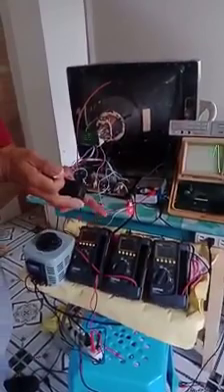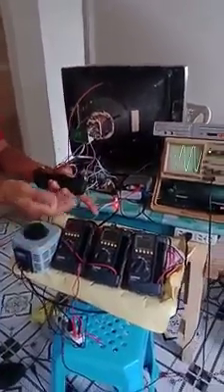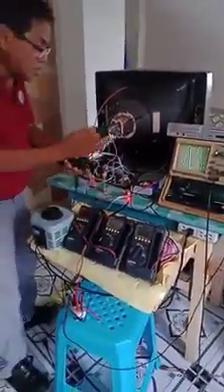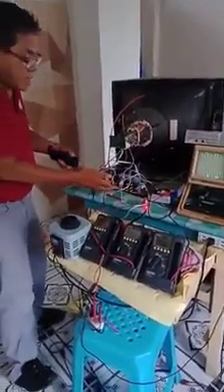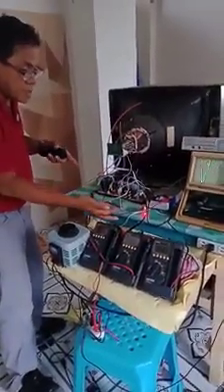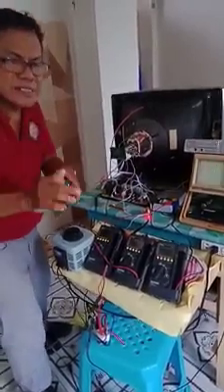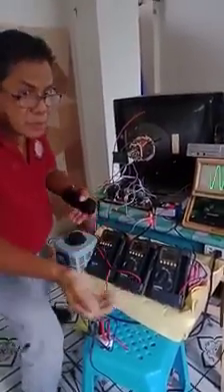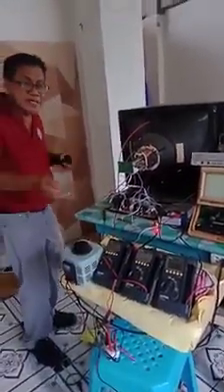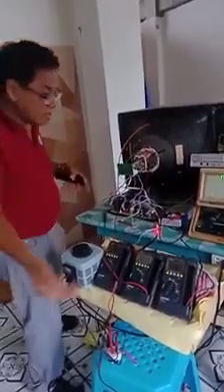Remember, the 38 kHz is omitted or filtered out as it passes the demodulator circuit, because what is needed by the TV receiver, as detected by the infrared sensor, is only the pulses. The 38 kHz is used only to carry the pulses to the TV receiver.